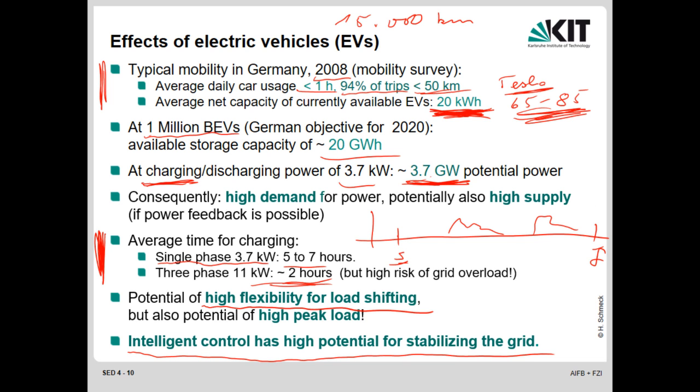If a battery is fully charged, and if it's standing around being fully charged, it's aging much more than if it would be just charged to 70% or something. So it is in the interest of the driver to state at which point in time you would like to leave again, because then you know that you have to provide full charge.